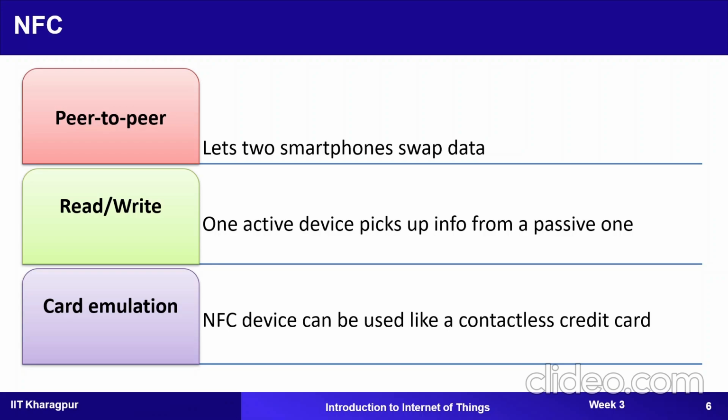The operating frequency of Z-Wave is 908.42 MHz in the US. However, it is 868.42 MHz in Europe. Mesh topology is used in Z-Wave, and it can support up to 232 nodes in a network. It utilizes GFSK modulation as well as Manchester channel encoding.